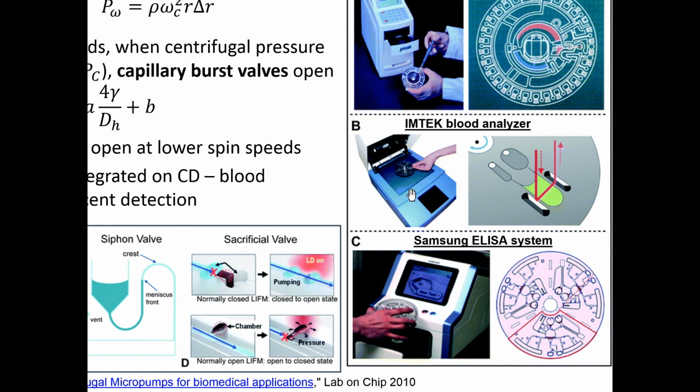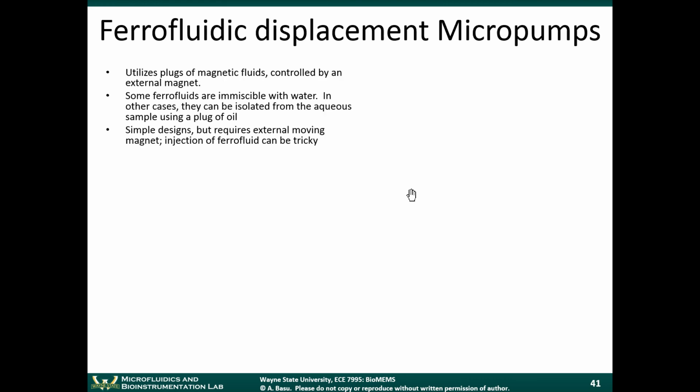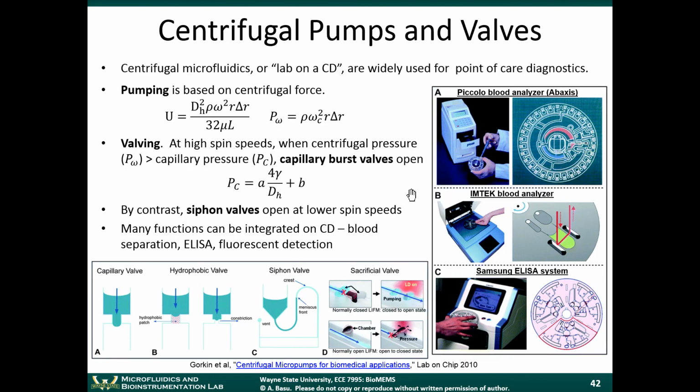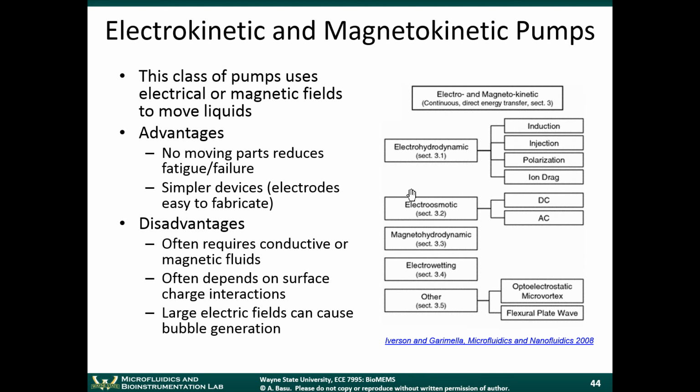So some of the detection stuff I mentioned, we'll be talking more about later in the module. So we're just about out of time here. So next time we are going to wrap up. This was the first example of a dynamic micropump where some type of energy is being added to the fluid directly. So next time in class we'll talk about other approaches, acoustic streaming micropumps, and then we'll get into the electrokinetic pumps, which is going to lead us into the next module